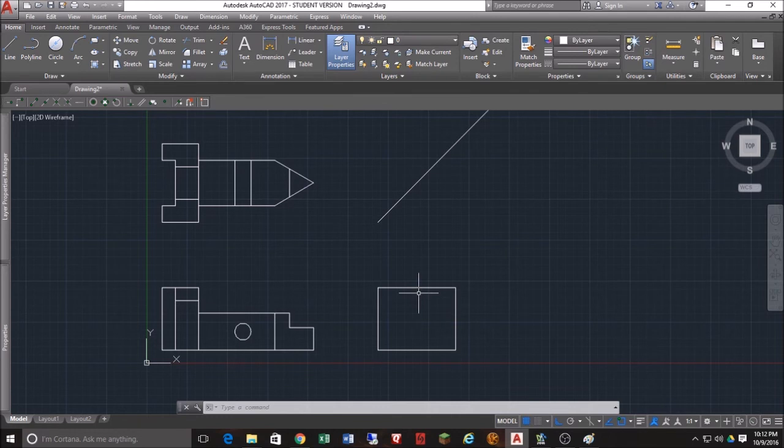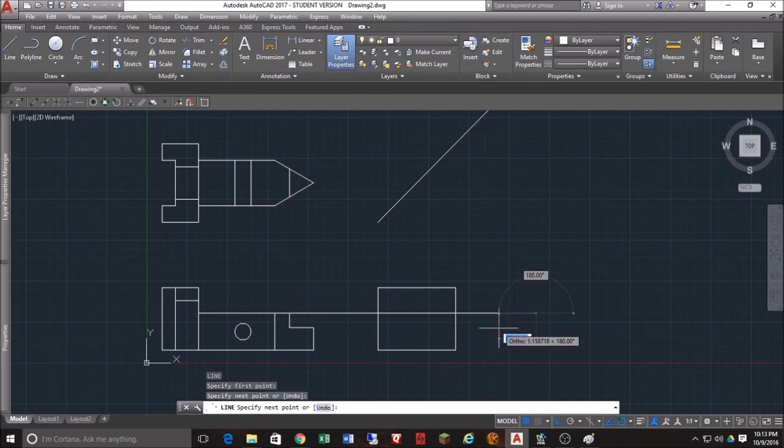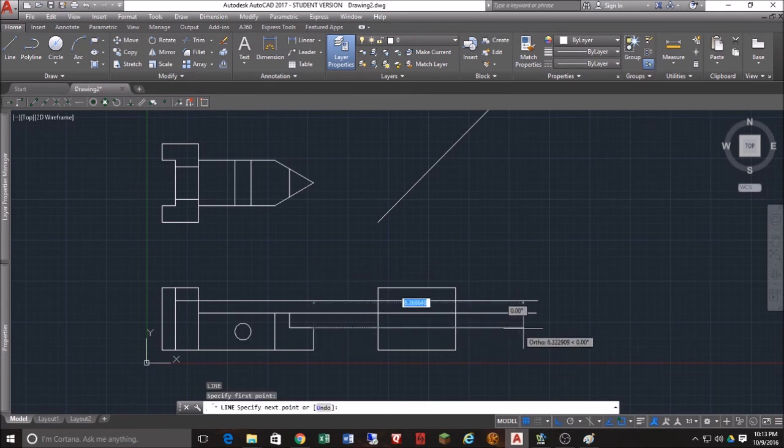So now we just need to do our right view, and then we're done with this drawing as far as placing all the features, and then we'll come back and we will set these hidden lines and then place our center lines and center marks. So first let's go ahead and we will project the different features over that we need. Like so. We'll come back for our circle, but let's get our main part looking more like the part.